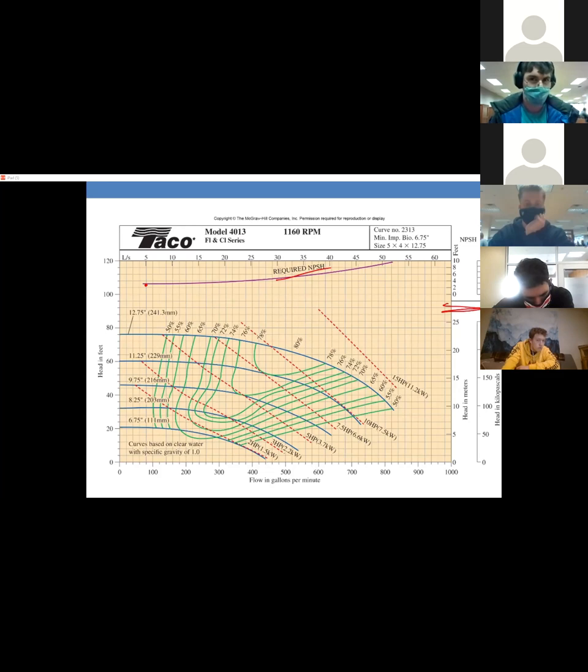We had one curve that came from the mechanical energy balance on the system and the other that came from the pump. It's sort of switched here, because these pump performance curves go down with flow rate, and this required NPSH curve goes up with flow rate.